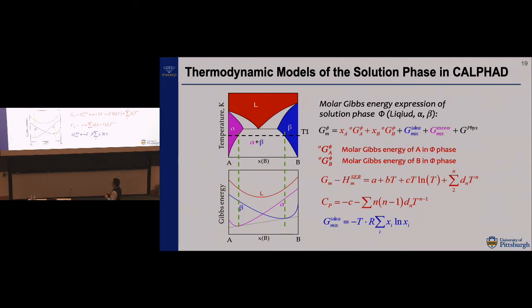How do you theoretically calculate the phase diagram? So basically, connecting these 2 points here is called a tie line, defined for the two-phase area, okay? So what we do theoretically is try to model the Gibbs free energy of each individual phase, okay? So we have liquid, alpha, and beta. And for the binary construction, you have to find the common tangent in order to define the tie line between alpha and beta. And of course, at different temperature, you can have different levels of Gibbs free energy. And if you shift to a slightly higher temperature, you probably end up with only liquid and beta. So these lines look different, but the principle is the same. Okay, so this is binary.